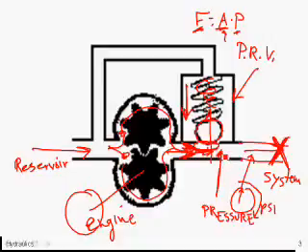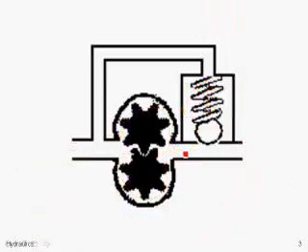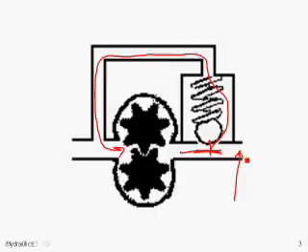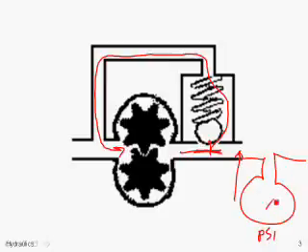in here, the force exerted on this ball will be high enough that it'll push the ball up. The pressure in here will go high enough that it'll push against the ball, the fluid, and it'll overcome the spring tension. The fluid will go around and come back into the pump. And what will end up occurring is on this system here, we'll have a PSI gauge, and it'll be relatively constant. A pretty typical transport category jet, big biz jet, big turboprop hydraulic system runs at 3,000 PSI.